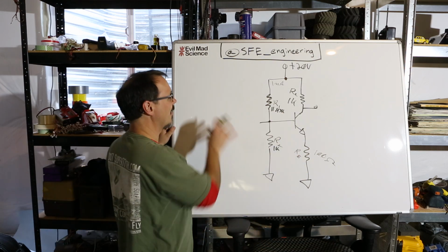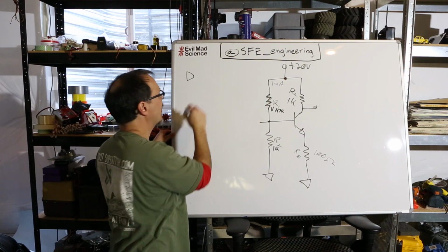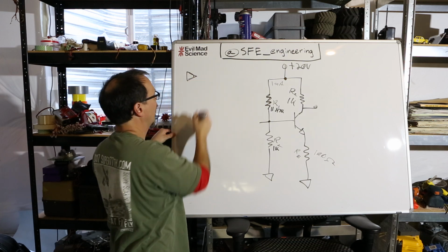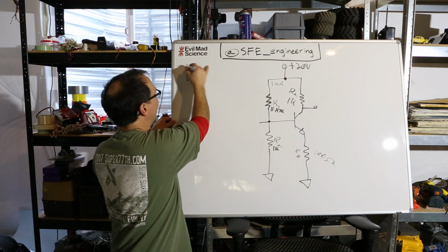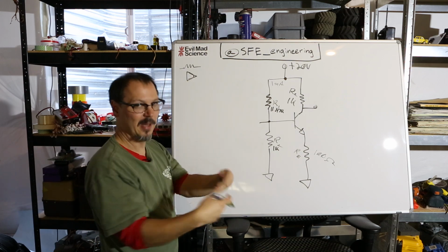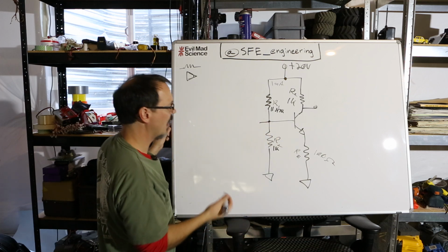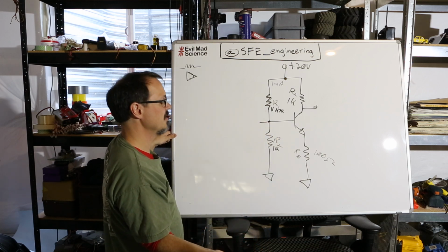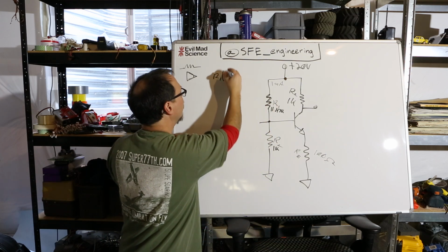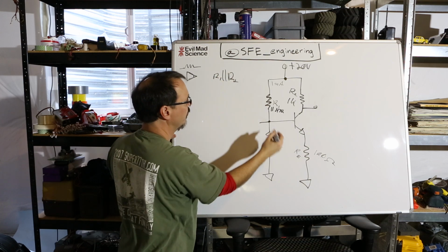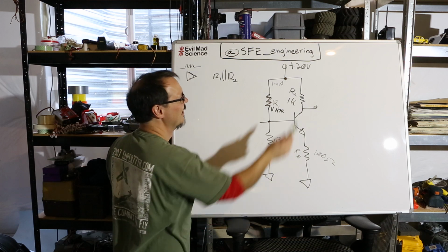I've got a signal generator and I need to get signal into this thing. My signal generator has an op-amp output, and so it's a really low output impedance, right? So the source resistance that this thing has internal to it is very small. They'll dump a lot of current without too much trouble. Now, the input impedance of this guy, which is basically modeled as a single resistor, is basically R1 in parallel with R2. See, so I'm backing up to basic principles.